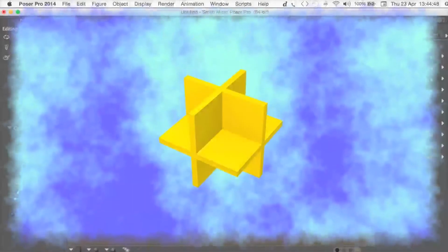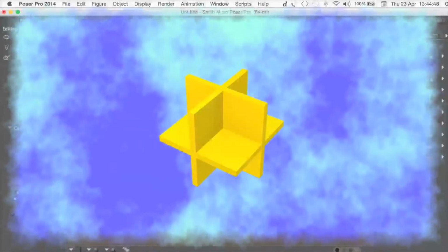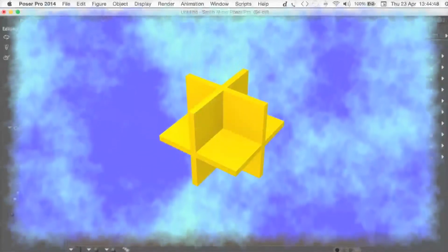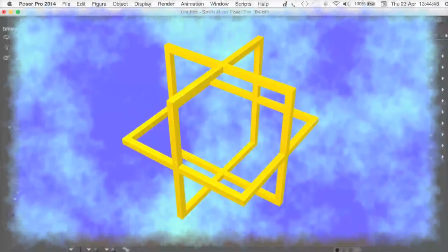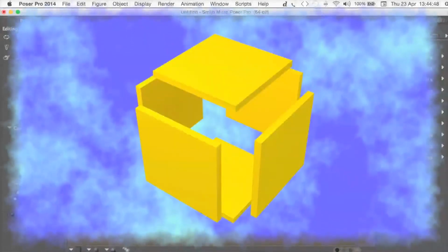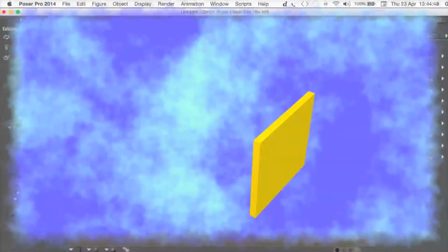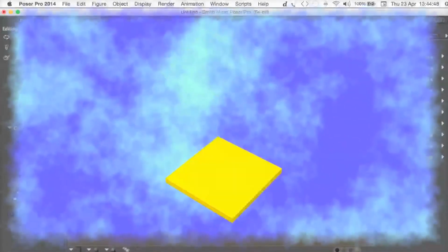There are 3 planes in the center. They mark the x, y, and z coordinates of the reference point of the object you want to measure. Surrounding these center planes there are 3 hollow frames, again for the reference point's x, y, and z coordinates. On the outside there are 6 planes for measuring the object's extent in all 6 directions: plus x, minus x, plus y, minus y, plus z, and minus z.